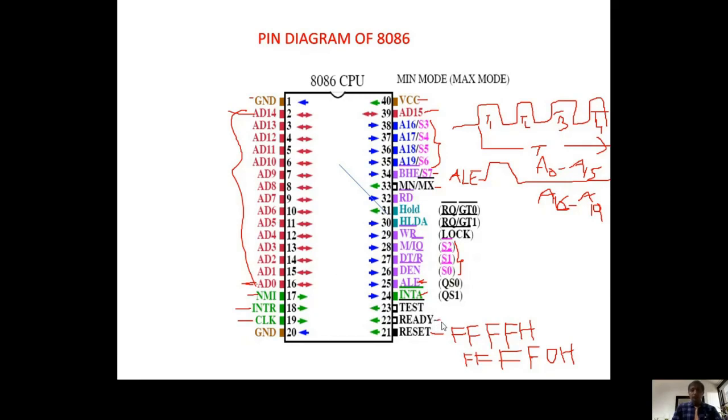If READY is activating, it indicates that external peripheral devices are synchronized to the processor. Okay, like that, READY is required. Next, the TEST bar signal. This is also very important.